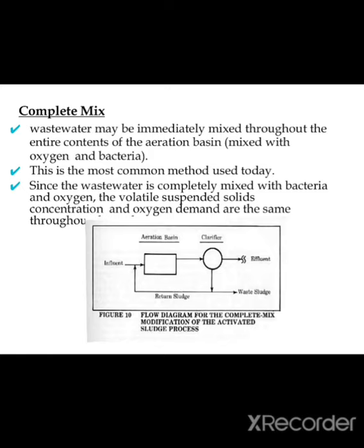The wastewater may be immediately mixed throughout the entire content of the aeration basin. This is the most common method. Since the water is completely mixed with bacteria and oxygen, the volatile suspended solids concentration and the oxygen demand are the same throughout the process.